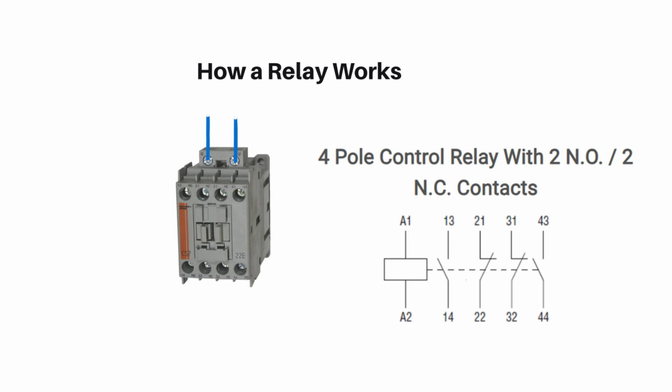That's the 2NC. So if you have equipment that you want to control using this relay, let's say you want to use this relay as a switch, you can connect your equipment or your component on the NO contacts. 13 is in, 14 is out.